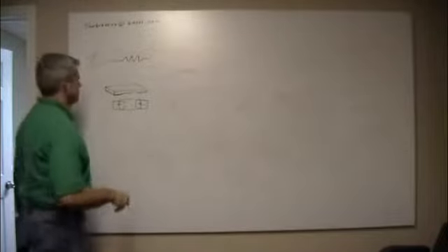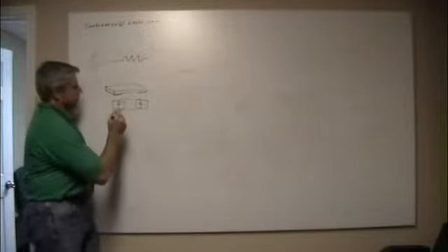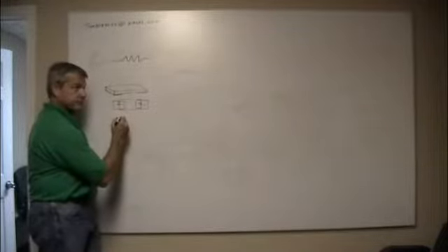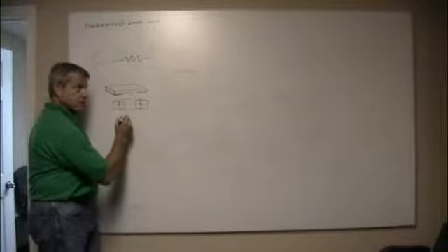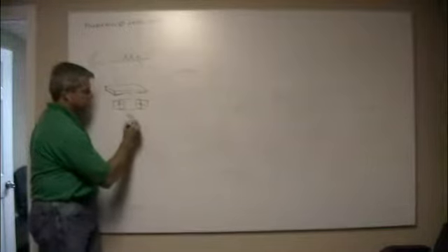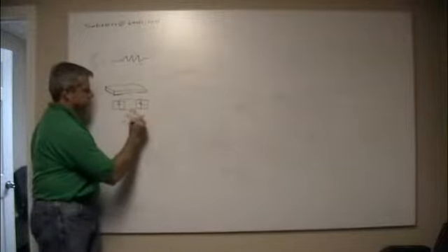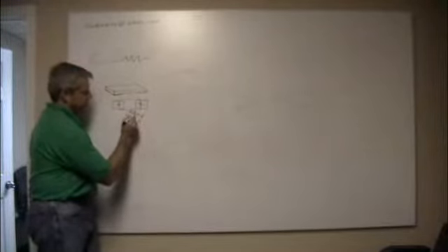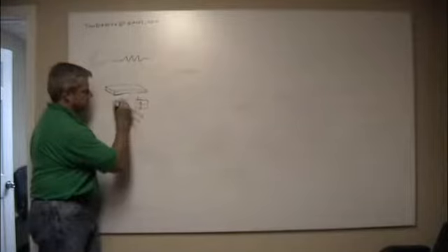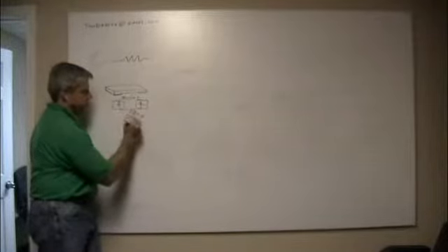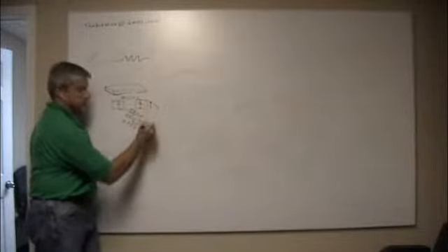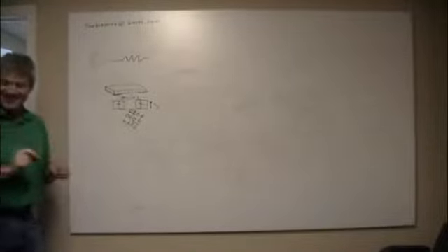I don't have a circuit board I could show you right now, but I've got a bunch, I just didn't think to bring one. These come in footprints, like 0603, 0402, 0805, 0603, and this is the first dimension in millimeters and the second dimension in millimeters, I think.